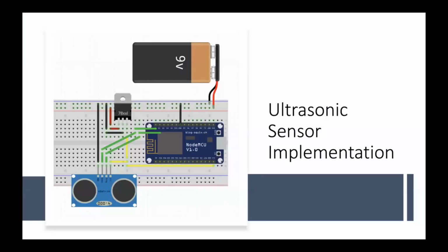The compatibility issue we had was the fact that the Arduino chip was not capable of providing the amount of voltage that the ultrasonic sensor needed, which is 5 volts. The only nodes that were provided inside the Arduino chip were 3.3 volts only. Not only that, but the ultrasonic sensor uses 5 volt logic, whilst the Arduino chip uses 3.3 volt logic.